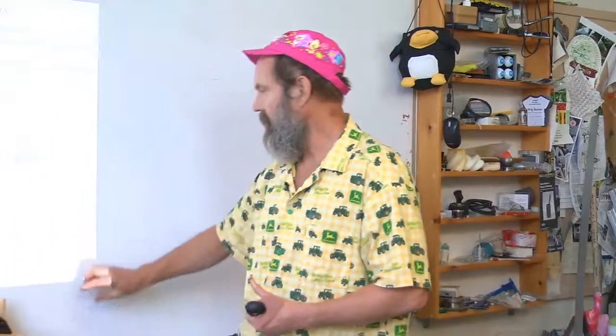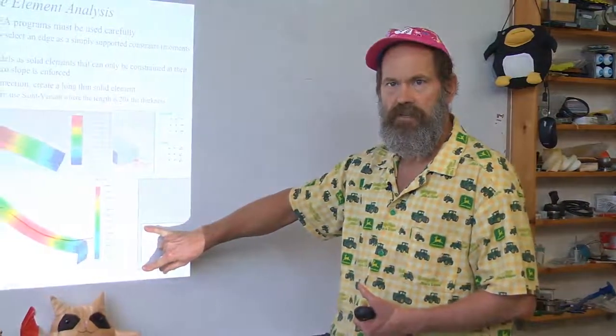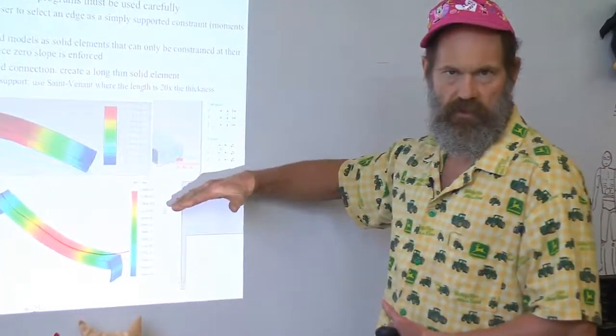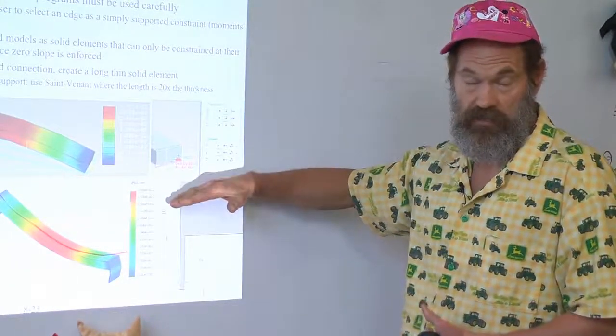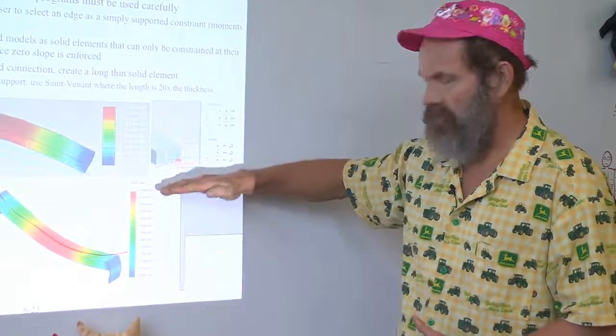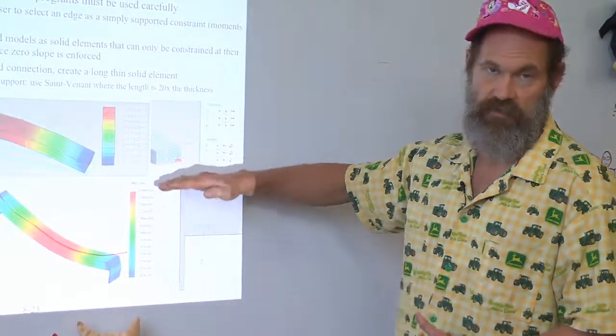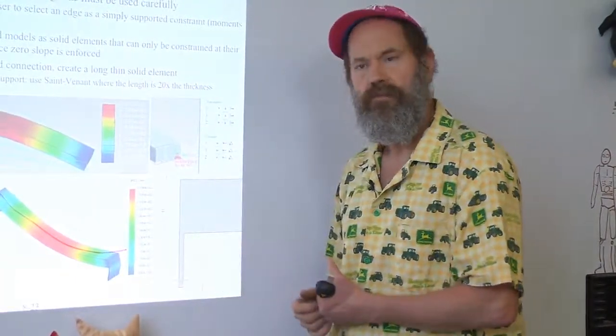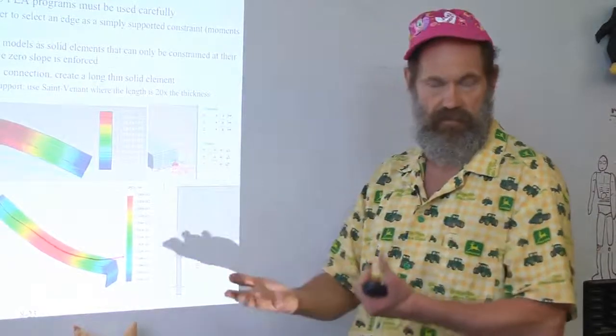So there are some tricks you can play when you're doing finite element analysis, where you're adding in compliance to free up the anchoring stiffness so it behaves the way it's actually going to behave in the machine, while maintaining, for example, the linear stiffness in the directions where you know it's going to be stiff. Similar modes of thinking for torsion. So do not be afraid in your solid model layout of your structure to add in compliance cuts, or compliance structures, to enable the finite element results to be accurate.